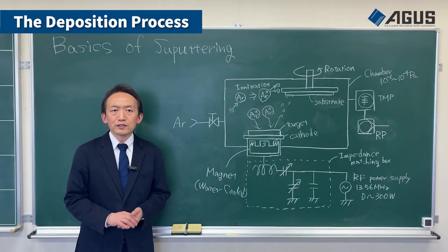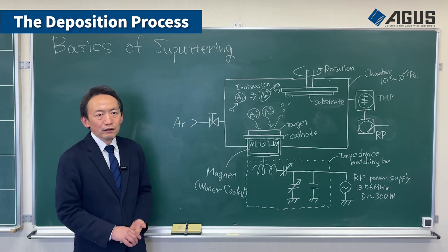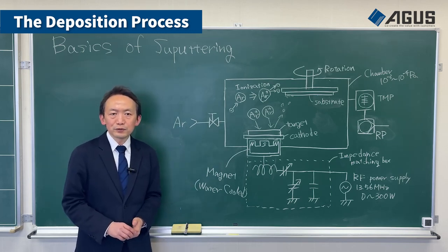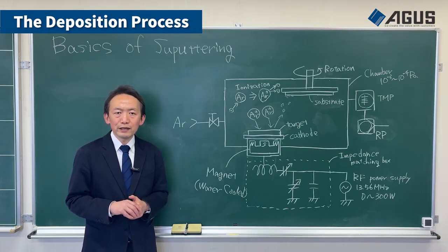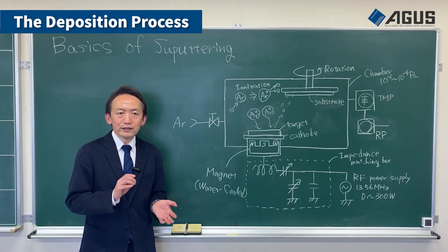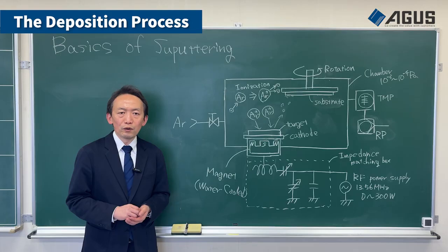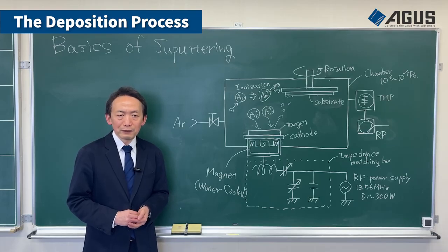Here is the process step by step using the SSP1000 sputtering system block diagram. First, place the substrate in the chamber. Next, vacuum the chamber down to 10 to the power of -3 or -4 pascals. This is called base pressure or background. Then, apply voltage to the target and open the gas valve. We raise the pressure to several dozen pascals to start the plasma.